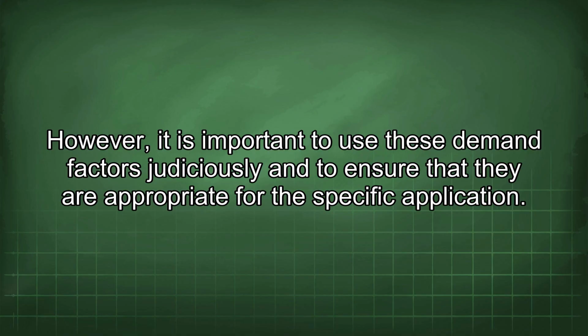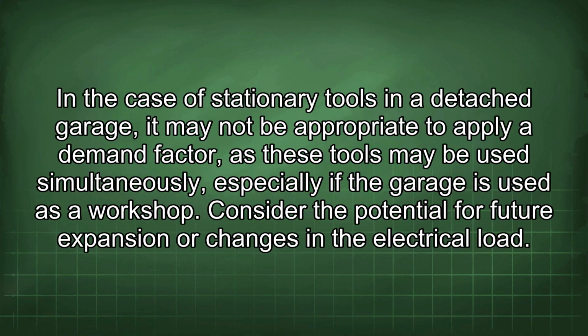However, it is important to use these demand factors judiciously and to ensure that they are appropriate for the specific application. In the case of stationary tools in a detached garage, it may not be appropriate to apply a demand factor, as these tools may be used simultaneously, especially if the garage is used as a workshop.